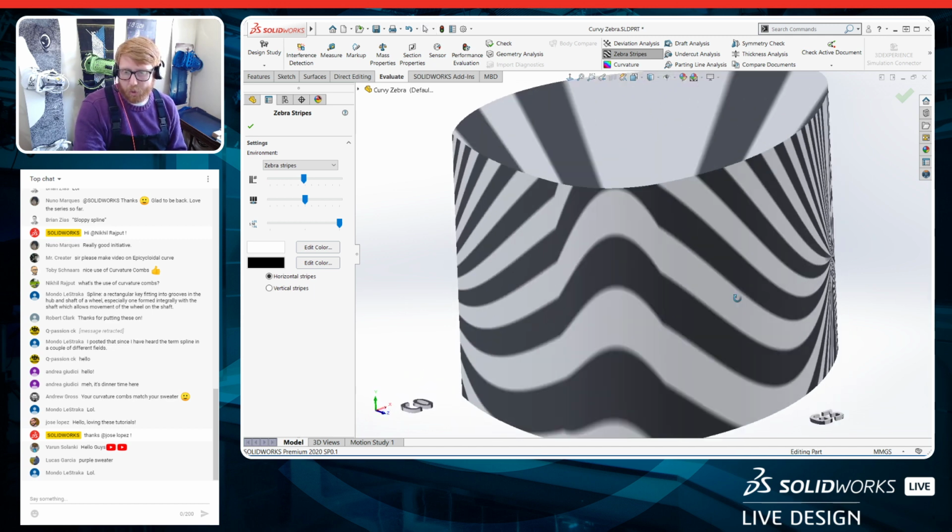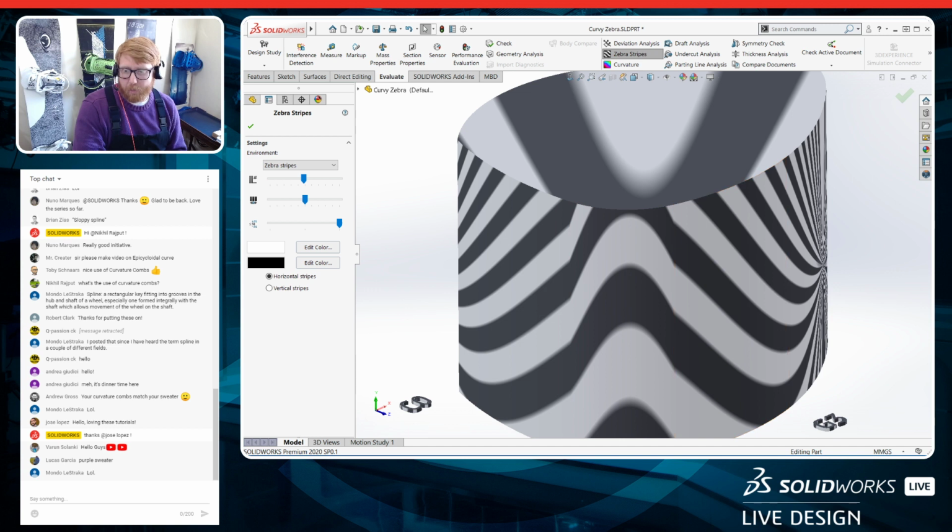Now in C2, they do match up, but you can clearly see where that edge is, right? So if you were doing a high gloss plastic, like this, for instance, is pretty high gloss, if I had a tangency relation right there, you'd be able to see it. There would be a seam line going down the middle of it. So typically we don't want that.